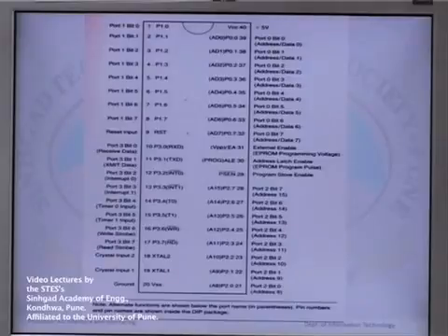After receiving this signal from the ALE pin, the external register, which is usually 74HCT373 or 74HCT375, which is nothing but the buffer, memorizes the state of P0 and uses it as a memory chip address. Immediately after it, the ALE pin is returned to its previous logic state and P0 is now used as data bus. That is, the data D7 to D0 is sent on these pins.